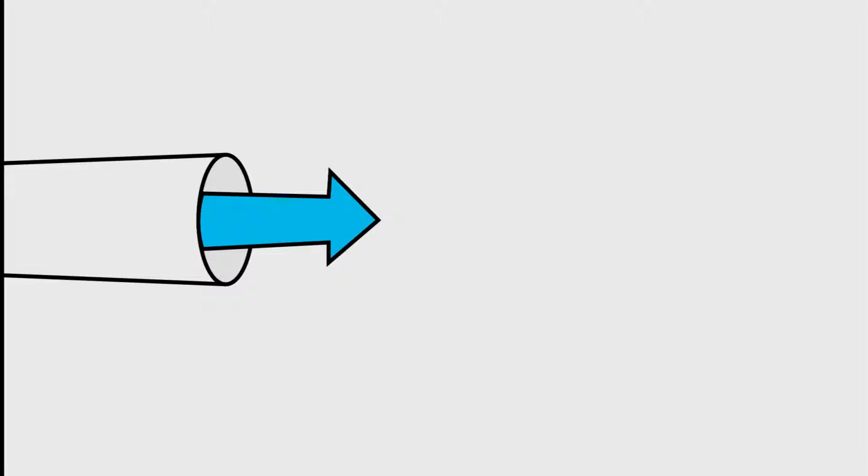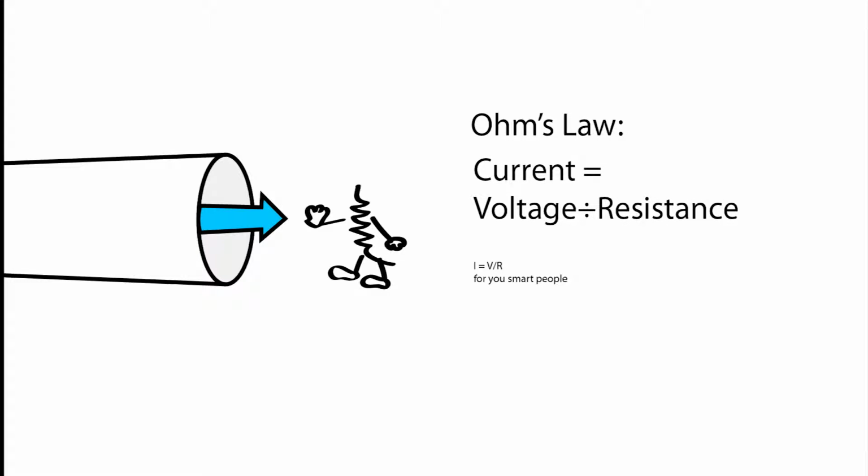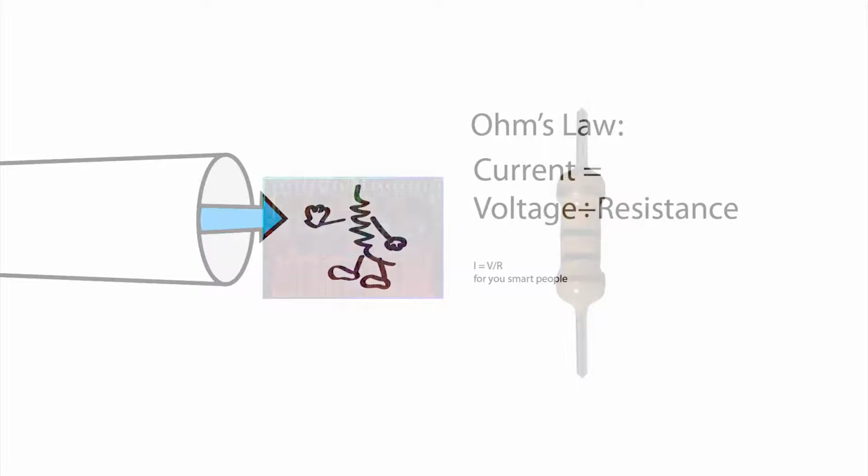Normally, to control current in a circuit, a resistor will be used, and they will act according to Ohm's law, which relates current to voltage divided by resistance. However, resistors are difficult to implement on ICs, and are sometimes impossible to manufacture due to the size constraints. So we use current mirrors and current sources to properly bias amplifiers on an integrated circuit.